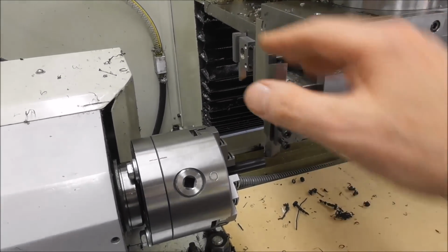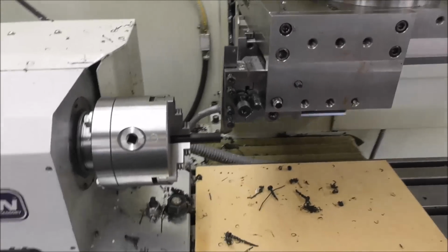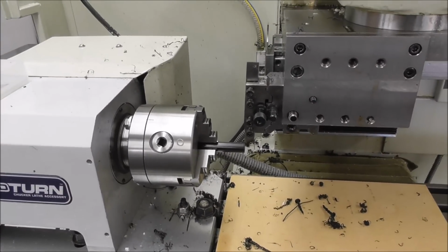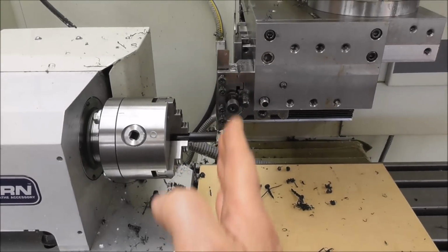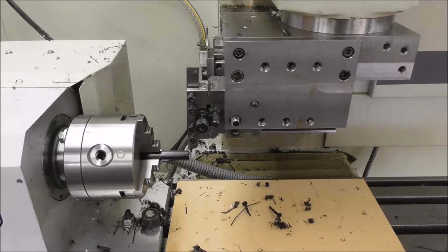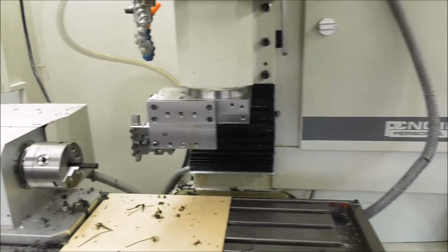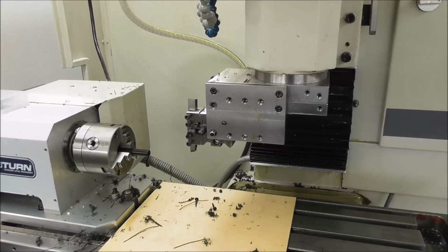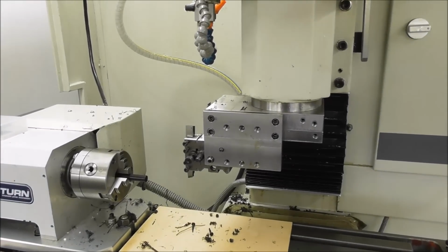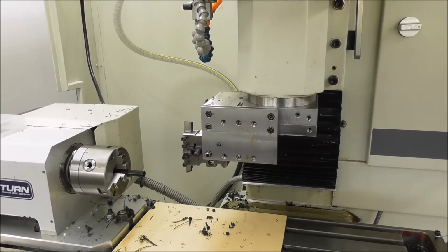So if you move the main DRO, see if I can show this graphically, the end of the tool is usually Z0. And we set it up on Z0. But if we move away, okay, so what I did here was I moved the Z 100 millimeters and clicked 0 so I could remember where it was. Now we can run the program in fresh air.